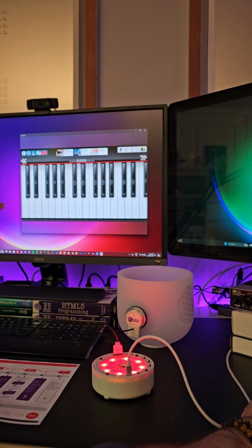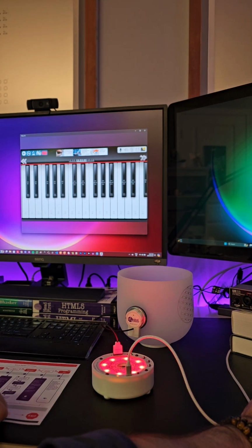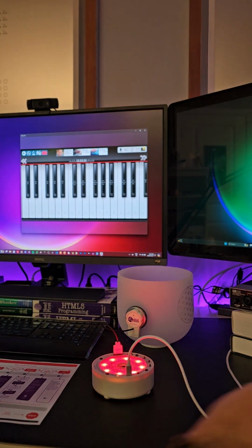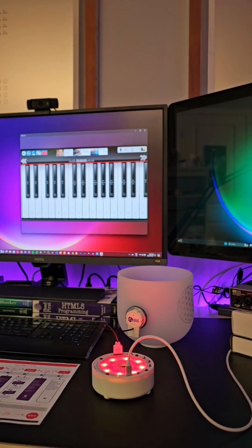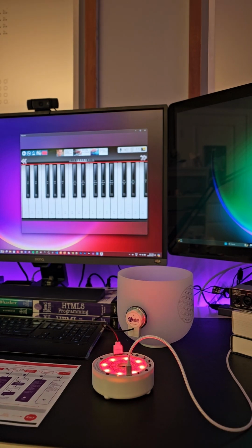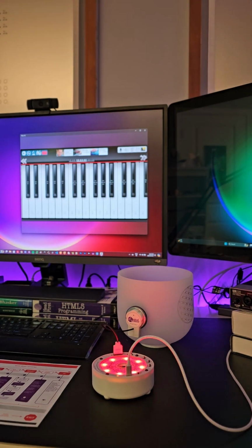So when I press the C4 note, it receives the MIDI message and it'll sound the bowl, in this case at full loudness. But we can also receive basically volume control messages over the MIDI port to modulate the intensity with basically like a slider. So that's possible as well. I can't do it with this specific keyboard, but I have other software where we can use the slider to modulate the amplitude. So once you have MIDI control, you're able to use sequencer software to have this thing play pre-recorded sequences or shows, which is quite nice.